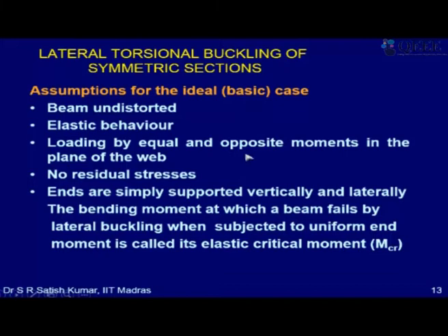And then it has elastic behavior. It should have a Young's modulus. Now we also have some more assumptions. Loading is done by equal and opposite moments in the plane of the web. So we want to keep the bending moment constant in the entire length of the beam. So we'll apply equal and opposite bending moments. So my bending moment diagram will be a rectangle for this simply supported beam.